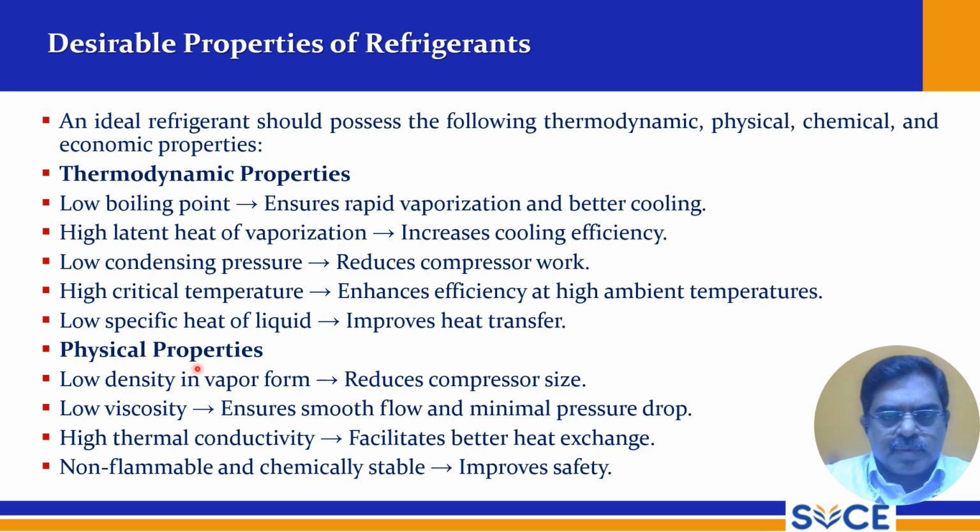In physical properties, low density in vapor form reduces compressor size. When we have low density in vapor form, then the compressor size is compact. We can have low viscosity, which ensures smooth flow and minimal pressure drop. High thermal conductivity facilitates better heat exchange. Non-flammable and chemically stable improves safety. So in safety norms, it should be non-flammable and chemically stable. So these are the physical properties, and we have chemical and economic properties as well. We will discuss them.